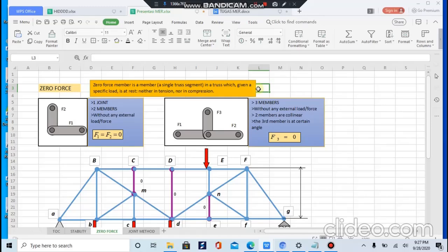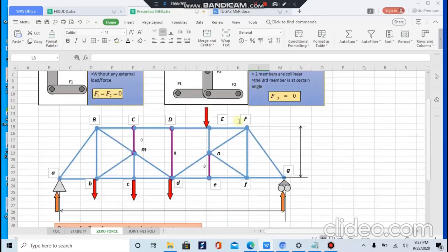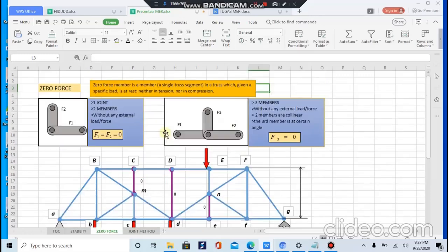In a truss, a zero force member is often found at a pin connection of the truss where no external load is applied and three or fewer truss members meet. Recognizing basic zero force members can be accomplished by analyzing the forces acting on an individual pin in a physical system, which include the zero force.